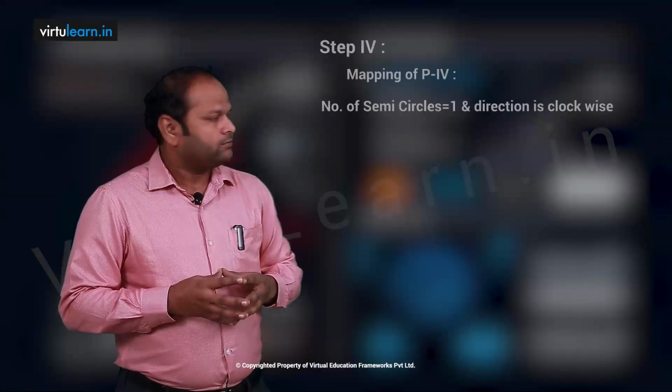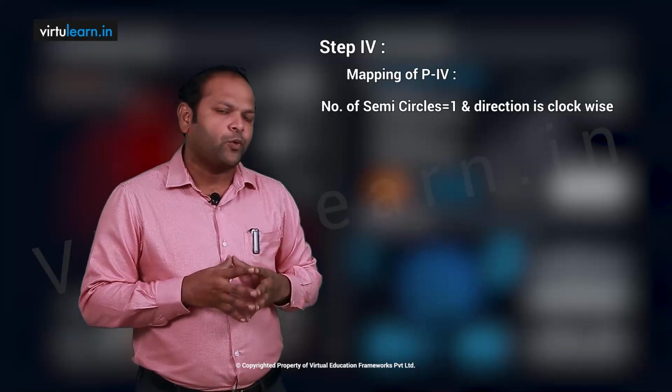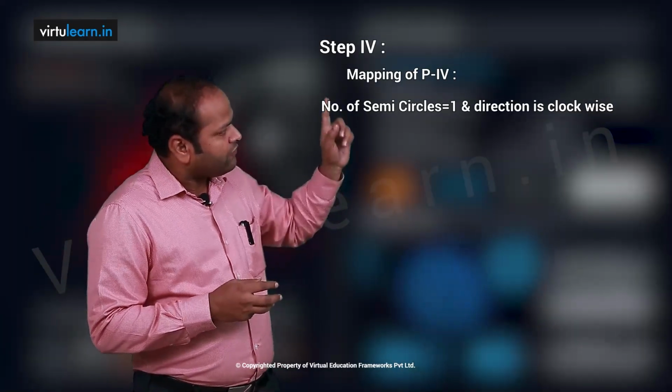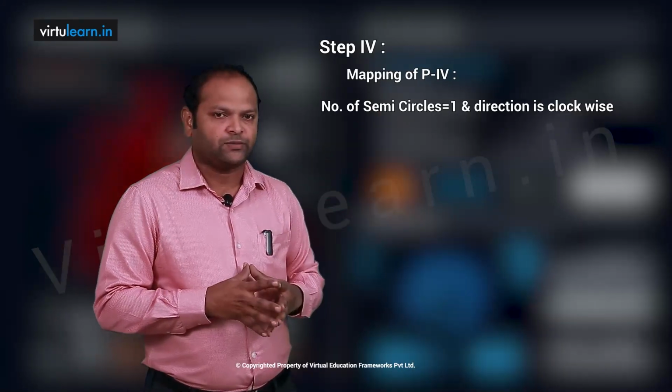Next, path 4. Before going to plot path 4, look at how many poles we have at the origin. I have 1 pole at the origin, which means we will have only one semicircle when you map path 4 into the GH of S plane.